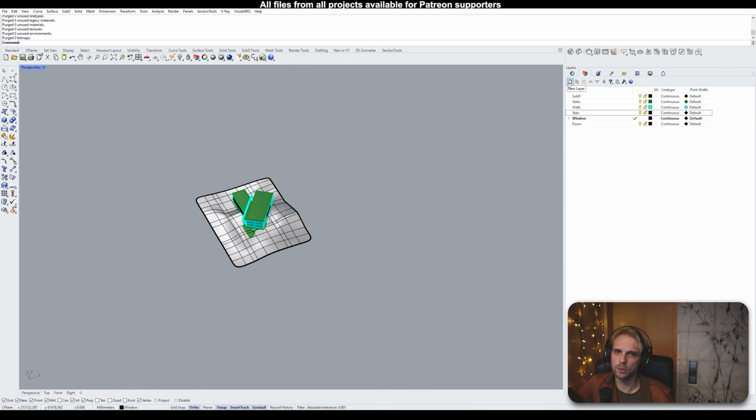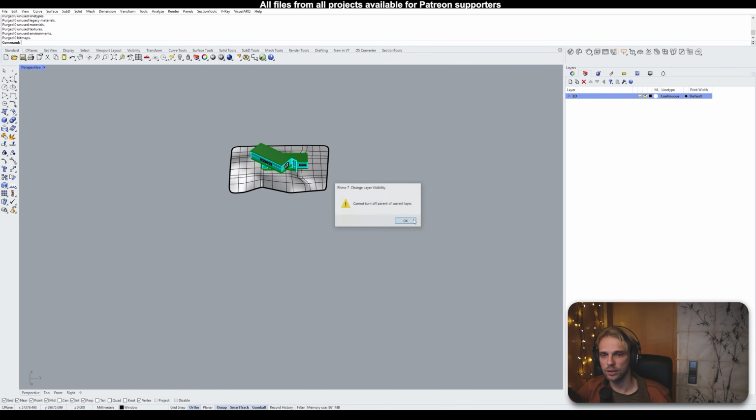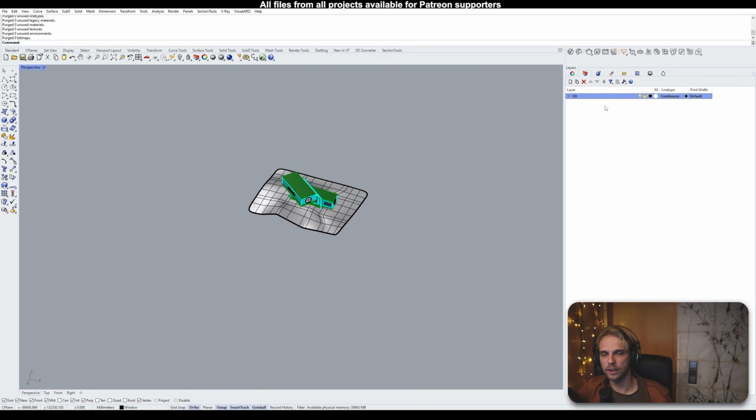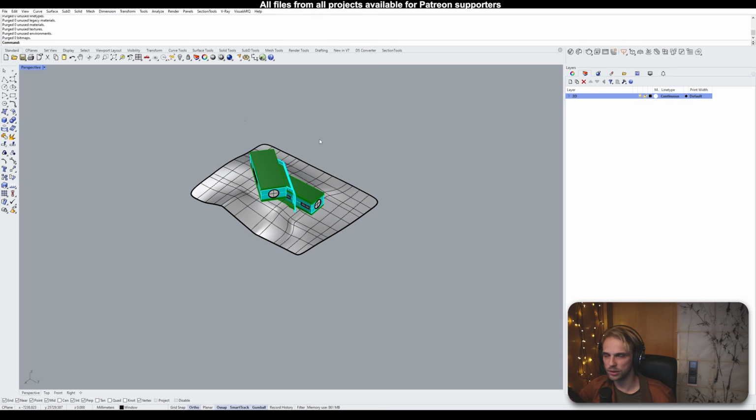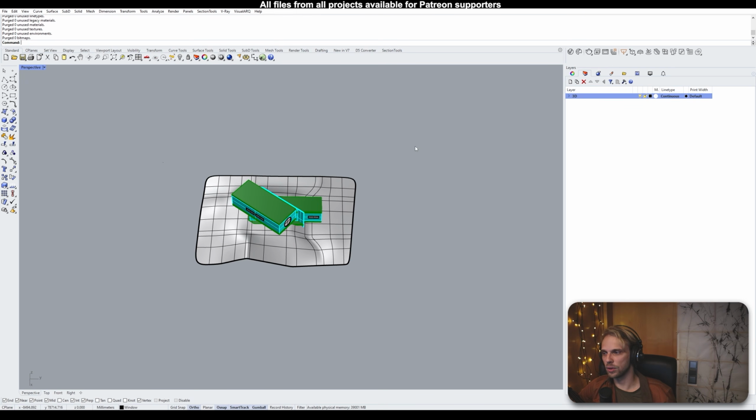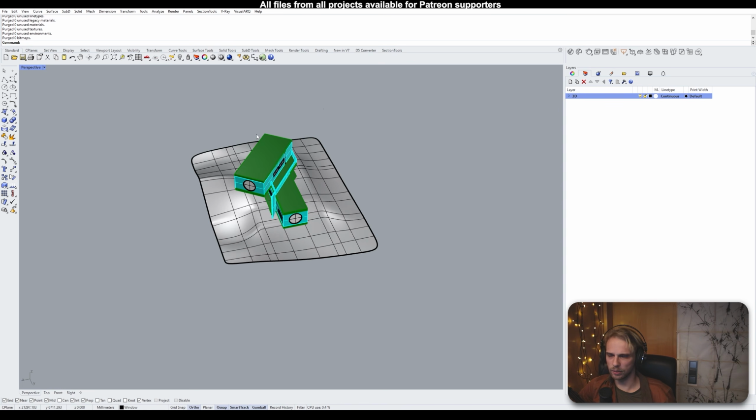All of these I will be placing into one big master layer, a new layer called 3D, capital D. I'll just select all of these layers and drag them into the 3D layer like that, so that I can easily turn on and turn off the 3D layer once I have more in here. Structuring your file is very important, and cleaning it up constantly is very important during the design process. Okay, time to create the drawings. So I'm going to make a clipping plane.